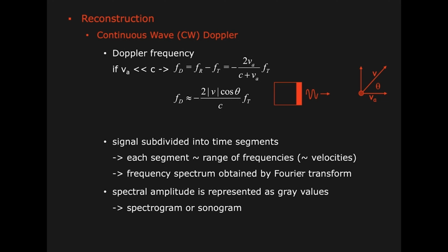So that means that there's no way we can use a broadband signal to look at frequency shifts. And neither can we look at frequencies that contain harmonics, because the change in frequency due to the Doppler effect is much, much less than this bulk effect of frequency-dependent attenuation in a broadband pulse, or the nonlinear propagation. So the only way to measure the frequency shift induced by the Doppler effect is if we